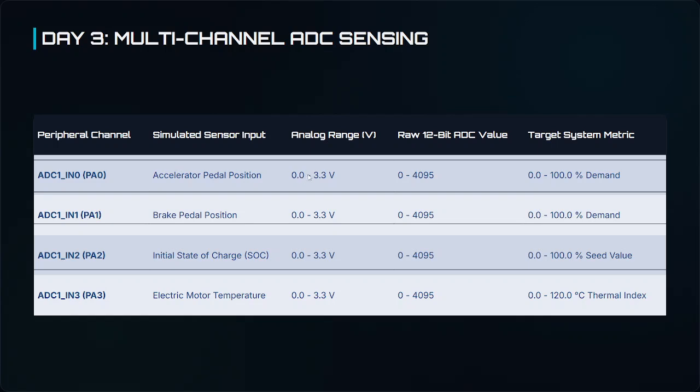These voltages are converted into discrete values from 0 to 4095. That means the greatest value, 3.3 volts, is represented digitally as 4095, the least value is 0, and the middle values fall between 0 and 4095.